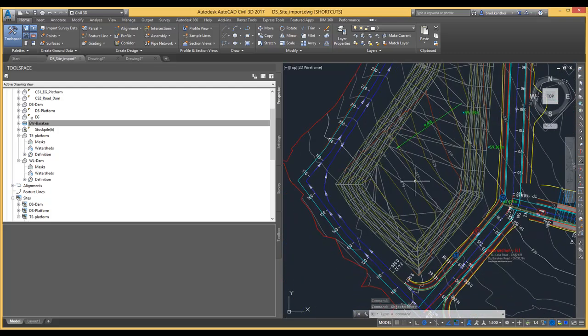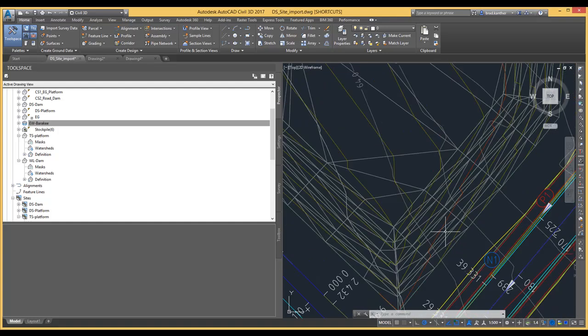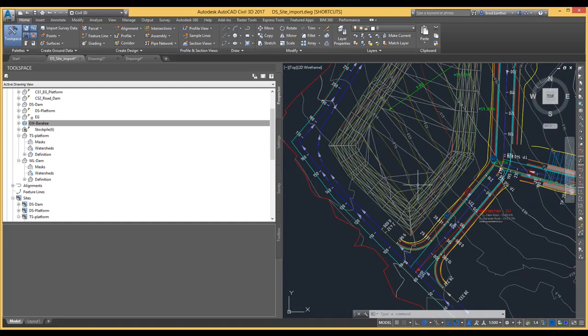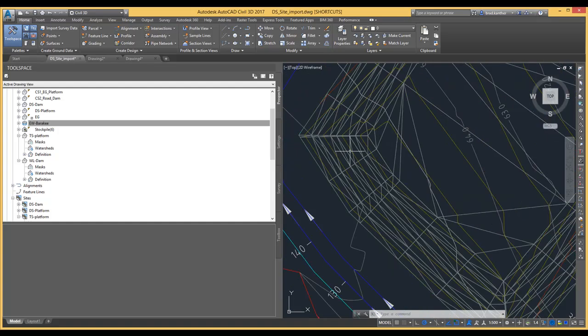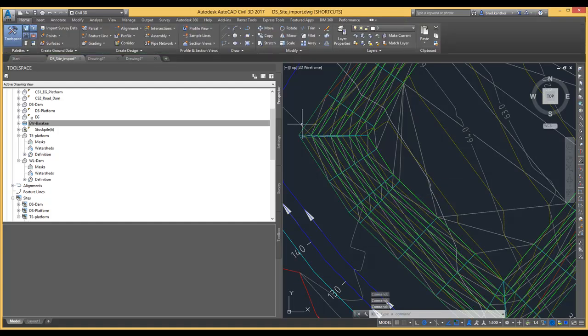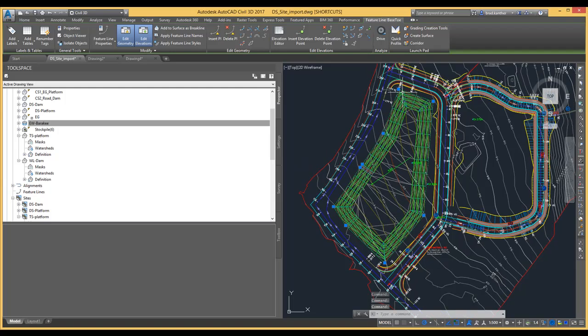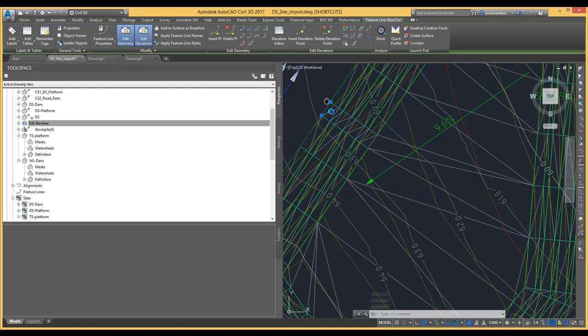Now the only catch is there's a few caveats here. Firstly, it only works with fixed links. So if I was to use a daylight on the inside or on an interior overlap, it won't work for daylight corridor assemblies. It'll only work for fixed corridor assemblies. Secondly, there are also some limitations to how this will work when we start adding curves into the mix. So currently this is just a straight line, vertex to vertex, straight sections.